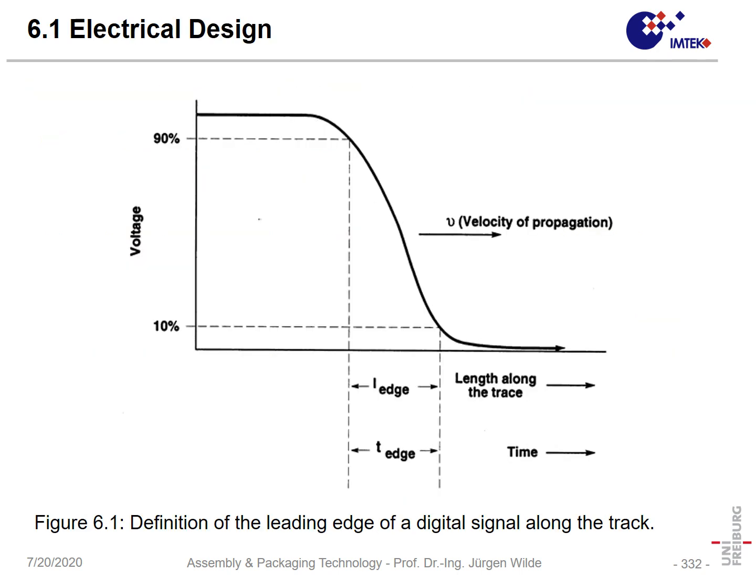The second is when a signal, which always has an electromagnetic wave around it, is moving into a certain direction on a conductor path, the voltage will never directly go from 0 to 1, or as we have in TTL level, from 0 to 5 volt, or from 0 to half a volt, like in a modern computer.